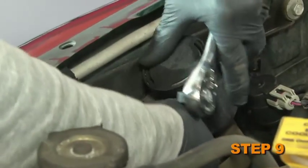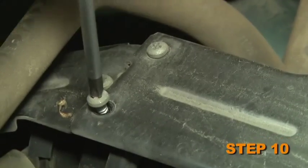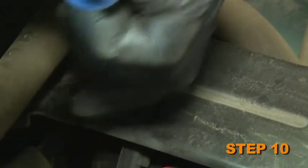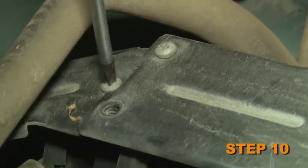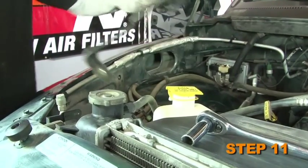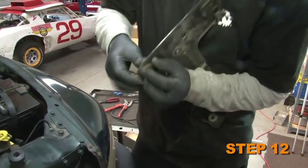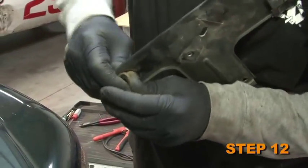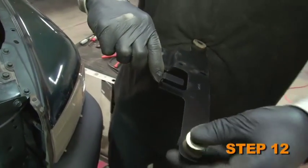Loosen and remove the evap canister vent from the evap assembly bracket. Loosen and remove the 3 screws that secure the evap canister to the evap assembly bracket. Remove the evap assembly bracket from the vehicle. Remove the 2 upper stock metal standoffs and the stock grommets from the stock evap assembly bracket and install them into the new evap assembly bracket.